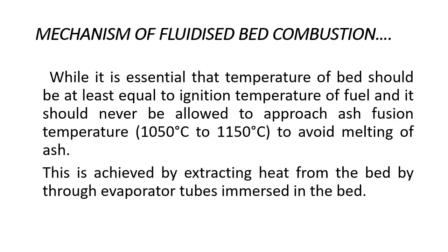While it is essential that the temperature of the bed should be at least equal to the ignition temperature of the fuel, it should never be allowed to approach the ash fusion temperature of around 1050 to 1150 degrees centigrade, to avoid melting of ash. This is achieved by extracting heat from the bed through the evaporator tubes immersed in the bed.